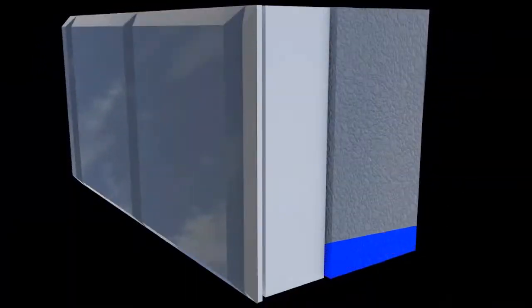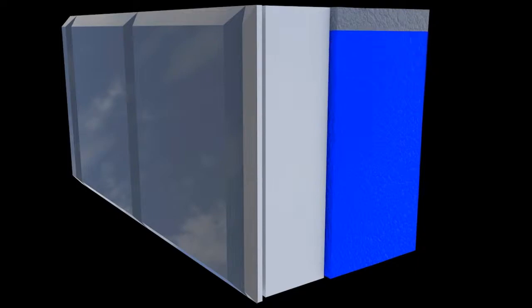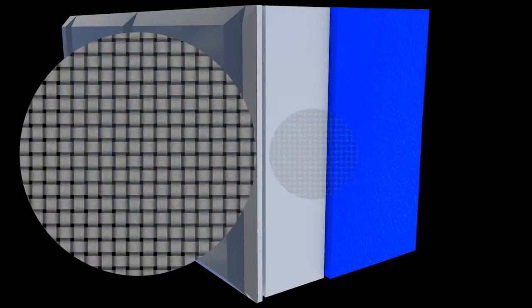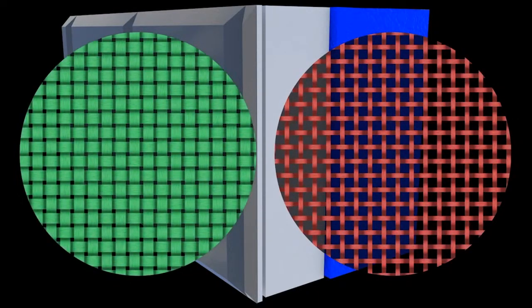This describes the ability of water to travel up through a building or material against the flow of gravity, like for example how water will wick up through a paper towel following the direction of the fibres. Capillary action works best with smaller pores rather than larger holes. For example, the fine pores found in brickwork or concrete provide an excellent mechanism to be used for this wicking action.